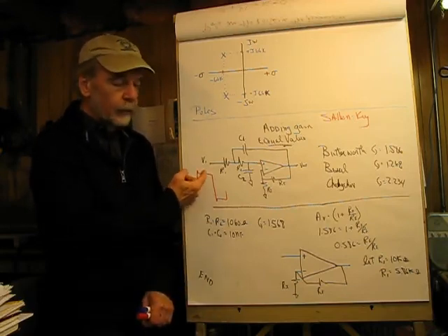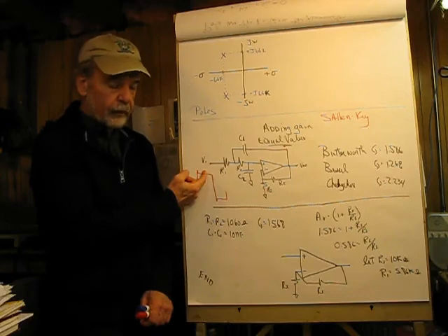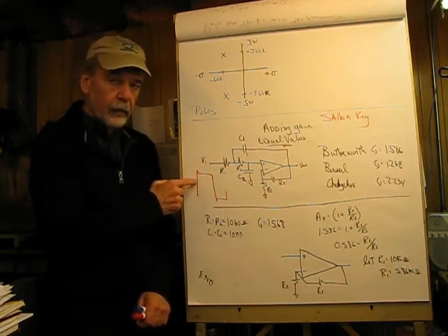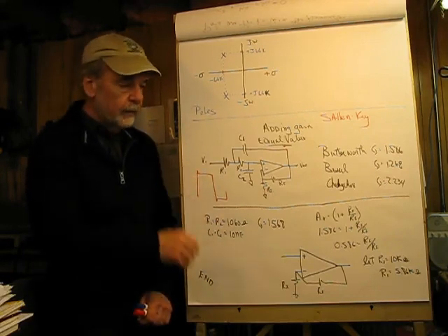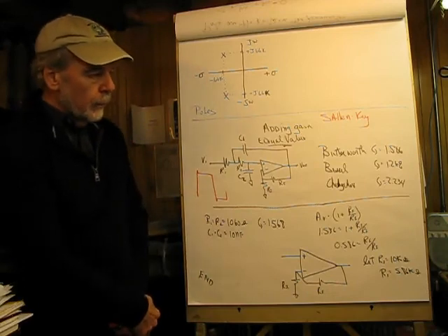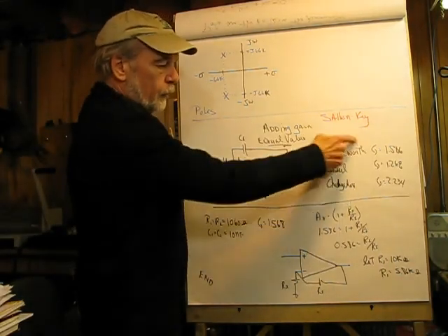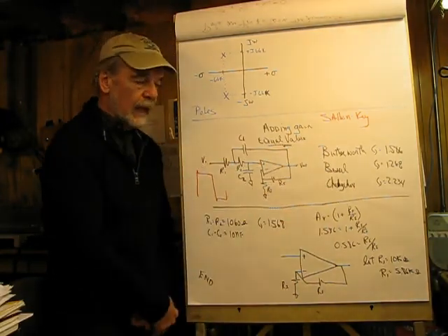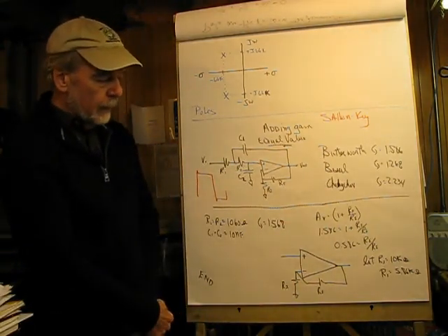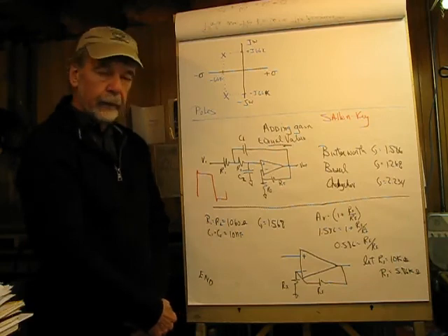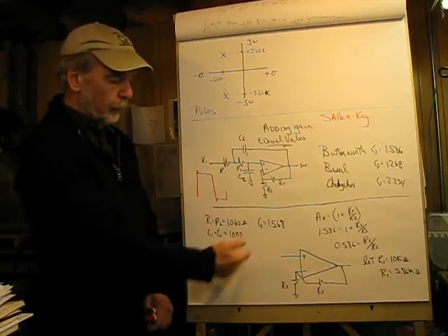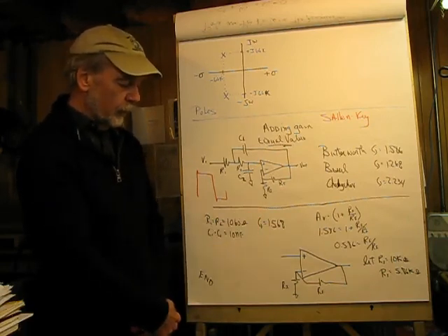It's not rounded, which would attenuate the high frequencies, and not overemphasized, which would accentuate them. So we have these standard gains, set up by the industry, and these are common names for common filter responses. Then the question is, how do I end up with a gain of 1.586 if I want to build a Butterworth?